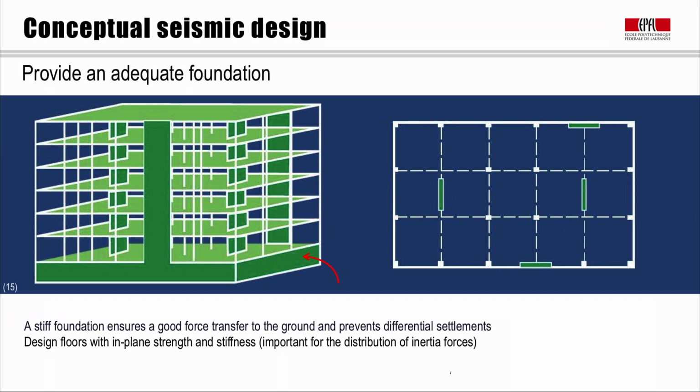So a stiff foundation ensures a good force transfer to the ground, and it also prevents differential settlements between the walls and therefore limits the damage to the building.